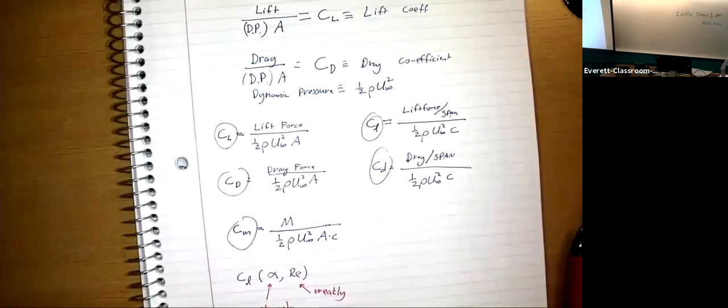As the wind turbine lives for 20 years, spinning at high speeds, hitting dust, having ice build up on its edge, it does a better job of maintaining a lift coefficient over 20 years. So now we need to study this new airfoil shape, and they built wind tunnels just for that.